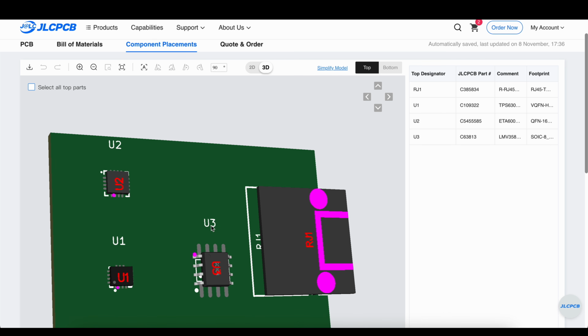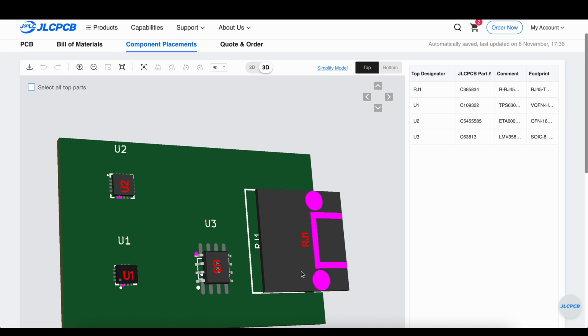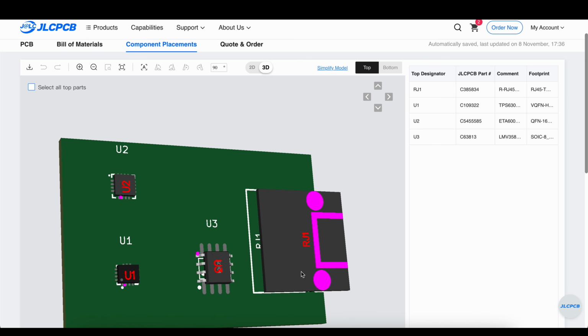Like if you just clicked next, next, next through this process, it might be okay with the Ethernet jack because that's placed manually. There's some components that are through-hole components that somebody physically has to place on there. But for a surface mount component, a pick-and-place machine is just going to follow your positions file, and there's no curing it. There's nobody who's going to step in and correct these errors after you submit go on this. So every time I use one of these components, I will have to come in here and adjust them.